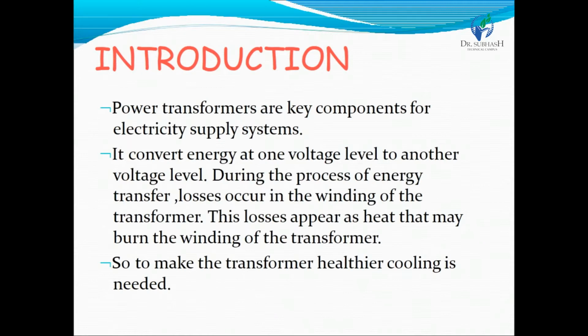For still larger transformers, the cooling oil is circulated in the transformer parts by means of an oil pump. A number of different combinations of oil natural cooling and forced air oil cooling are available in the market, and we choose them based on the size of the transformer and the demand of the particular application. They are divided into various cooling methods.